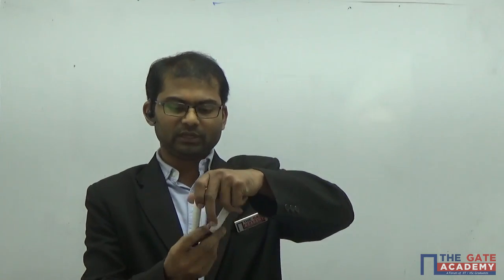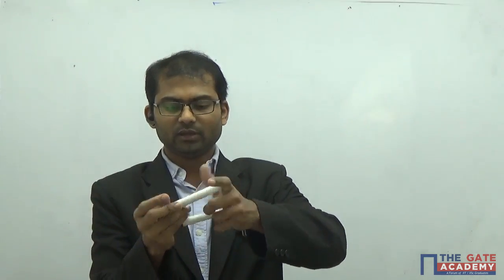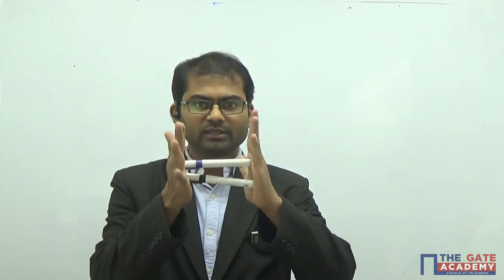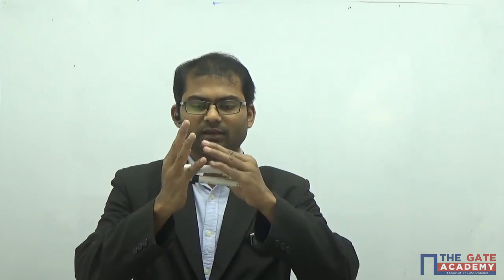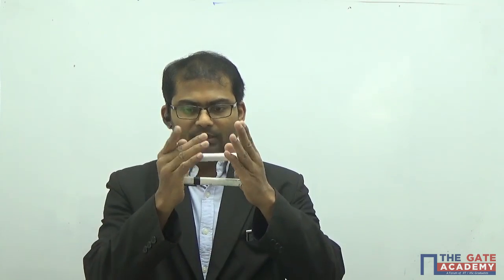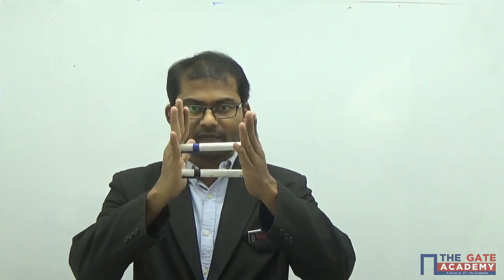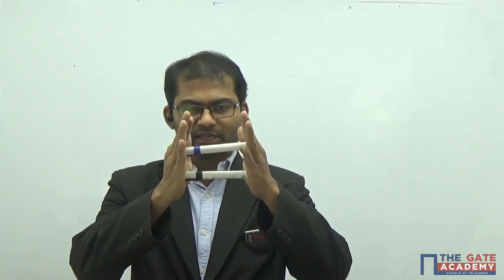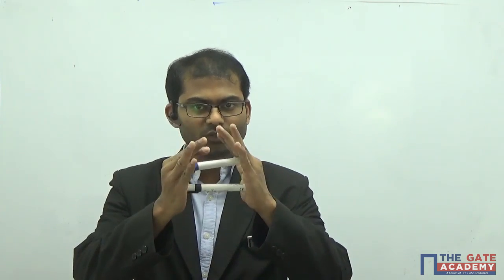Okay. This was very simple here. We don't have any questions also in the previous GATE papers. So shafts in parallel means basically the idea we get is we have to put one shaft and another shaft, both parallel in this way here. If you put it in this way and try to apply torsion like this, understand, this is a very very complex thing. Actually if you apply the torsion in this way, with shafts parallel in nature, instead of creating torsion, what's happening is they're experiencing bending basically. So this is not the way of dealing with shafts in parallel in the subject of torsion. You have to go in the other way here.